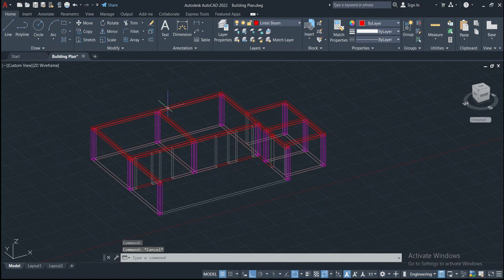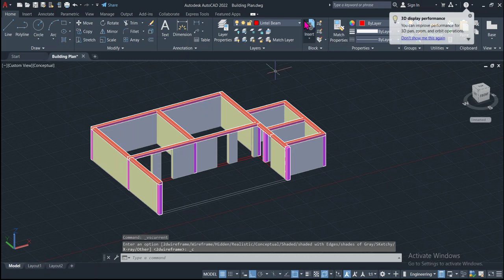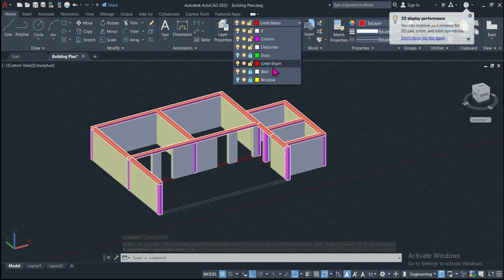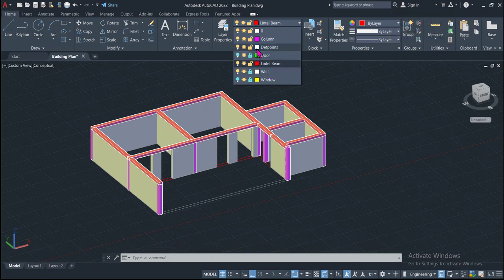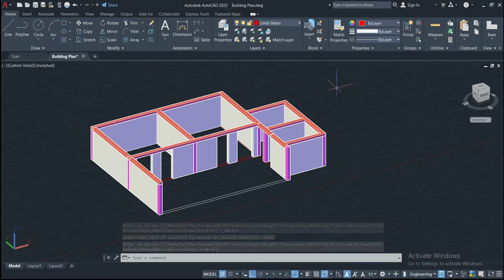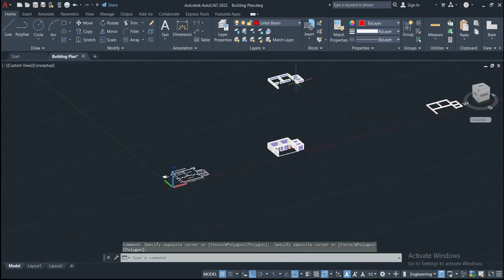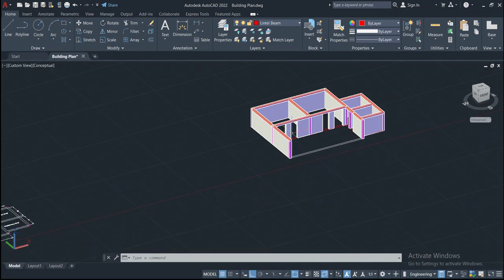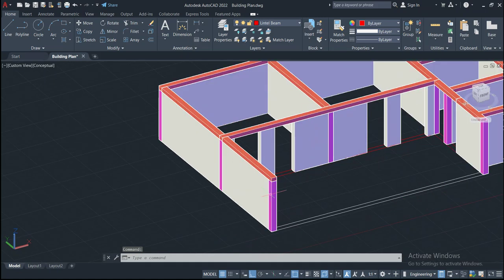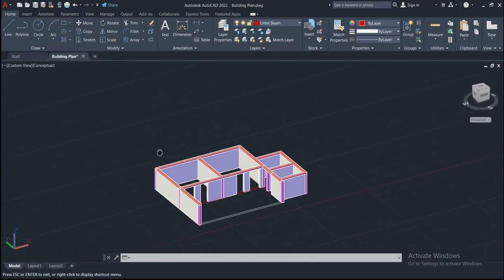So till now the columns and walls till the 7 feet height have been plotted, and now we are going to paste the walls that we have constructed, this one, above the lintel beam to fulfill the remaining walls to reach to the ceiling level.